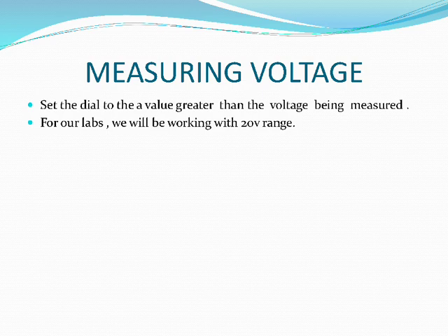Measuring voltage. Measuring voltage is the same as measuring resistance. Set the dial to a value greater than the value of the voltage being measured. For our labs, we will be working with the 20V range.